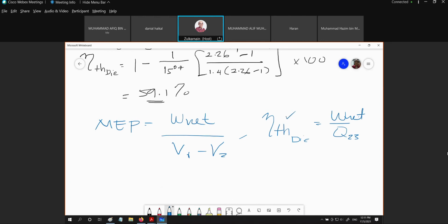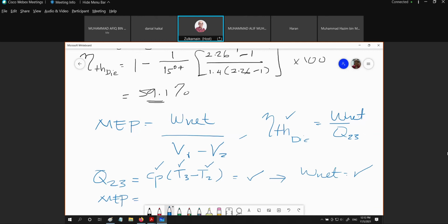You already have this value, right? So you need to solve the Q23. What is Q23? The Q23 is equivalent to Cp times (T3 minus T2). Okay, you know your Cp value, you know your T3 and T2, then you will get your Q23. Once you have your Q23, you will get your W net. Once you get your W net, then solve for your MEP, and try to get it with the appropriate unit. So in this case, T3 is given, T2 we have got it. Then you can solve for your MEP.